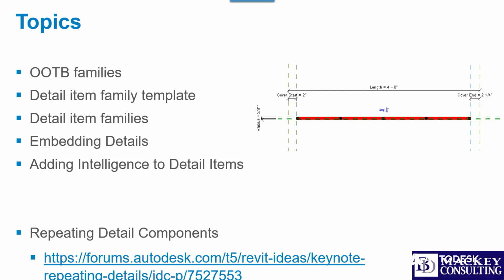So for me, I go in and I start tweaking the object styles. I don't want it to say medium, thin, light. I say pen 1, pen 2, pen 3, pen 4, etc. That's my personal opinion. But a lot of them started with the out-of-the-box family. So as you're going down this process, use those, get started with those, and start going into it.